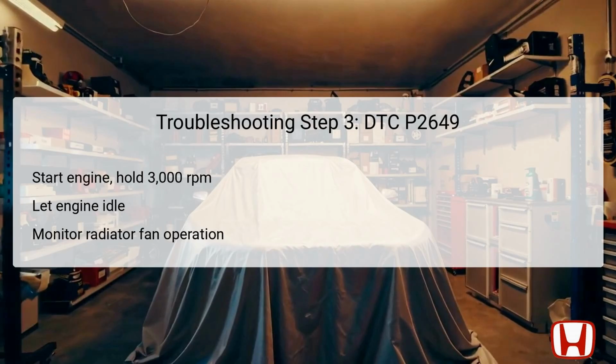Once the ignition and DTC clearance process is complete, start the engine and hold the engine speed at 3,000 RPM without load. Holding the engine at this specific RPM allows the technician to simulate conditions that may strain the system, testing the solenoid under operational demand.